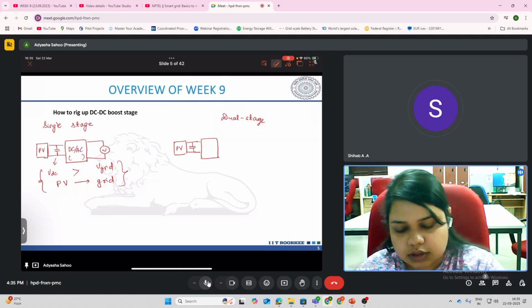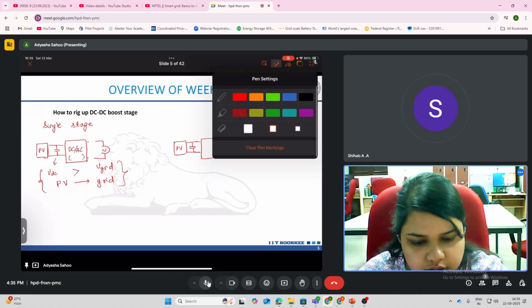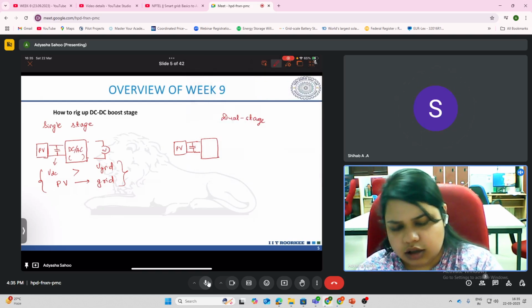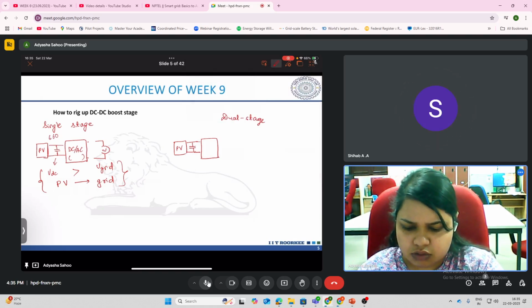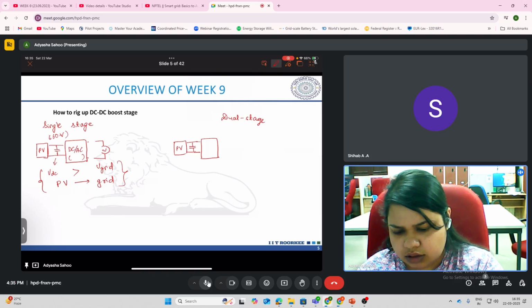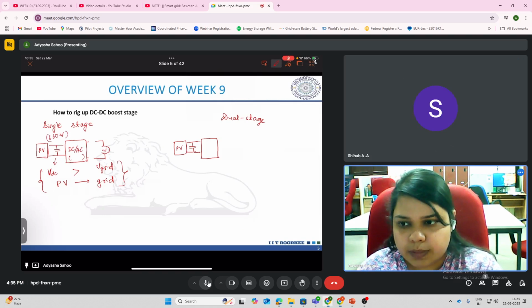This is the AC side, but we calculate the equivalent DC side voltage, and it comes around in the range of 600, if I'm not wrong, 660 volts. I think the DC link voltage should be greater than this 660 volt at all times.